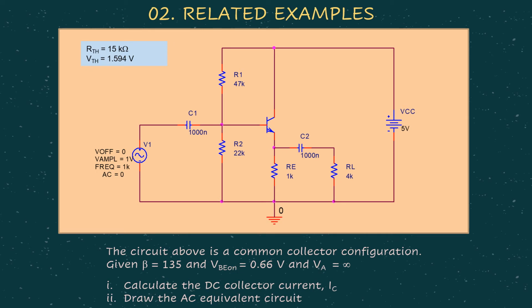We are going to consider both voltage gain and current gain for us to see related to this common collector amplifier. As you can see from here, you straight away know this is a common collector amplifier because the load resistor is connected at the emitter terminal. So whatever gain that will be calculated from this particular circuit should always be positive. If you are getting a negative value, obviously your analysis is wrong because the gain should always be positive.